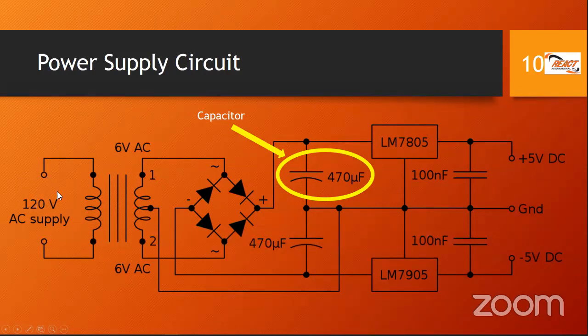So even though you might have removed or unplugged the device from the wall outlet, don't for one moment believe that there isn't some voltage inside the device. Just be careful, be mindful that you have things like capacitors inside devices, so even though you switch it off or unplug it, there may be dangerous voltages still inside the device because of things such as capacitors. So always be mindful that there are devices, even though unplugged, where there might be a voltage inside that can zap you. So please bear that in mind in terms of safety.